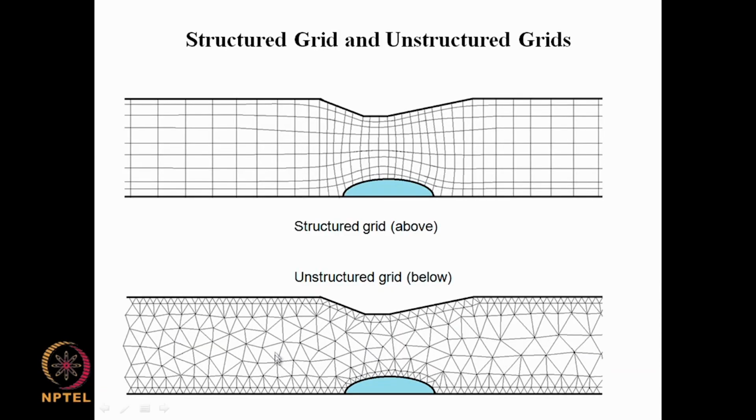And as opposed to that we have an unstructured grid. In the case of a structured grid, for example, you have this point here and you have a neighbor here and a neighbor here, and all those neighbors are known. The neighbors are known by the coordinate line on which they appear. For example, for this point the immediate right neighbor is the one at the next coordinate line in this direction, and the immediate top neighbor is in the next coordinate line in the j direction. The immediate left neighbor is the coordinate point intersecting the same j line corresponding to the i minus 1 coordinate line. So the immediate neighbor information is known here, and each point has 4 immediate neighbors, and maybe 4 corner points and so on in 2D.